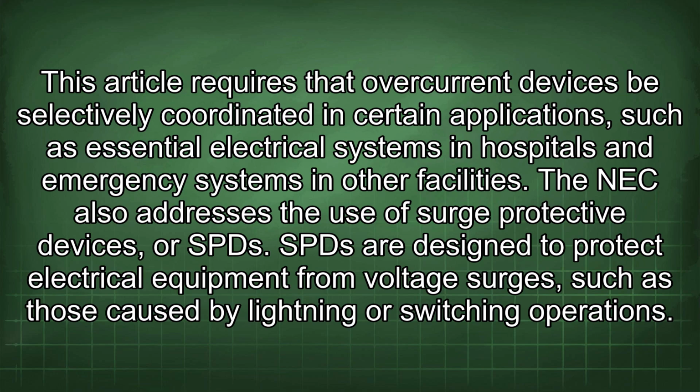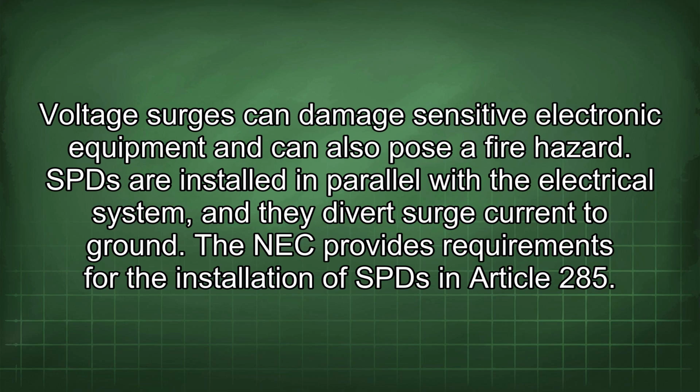The NEC also addresses the use of surge protective devices, or SPDs. SPDs are designed to protect electrical equipment from voltage surges, such as those caused by lightning or switching operations. Voltage surges can damage sensitive electronic equipment and can also pose a fire hazard. SPDs are installed in parallel with the electrical system, and they divert surge current to ground.